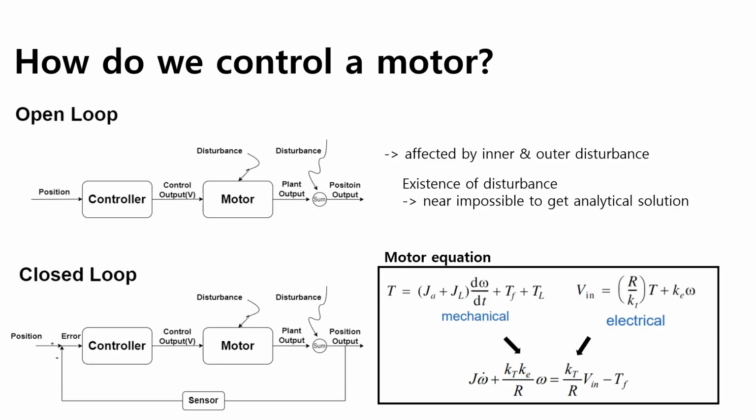This ODE is the motor equation. We can change the input or the voltage to control the output or the angular velocity of our DC motor. We can also call the output the response of our motor. We can represent this as a block diagram, as shown in the picture on the top. This is called open loop control, where we are supplying the voltage to the motor blindly.